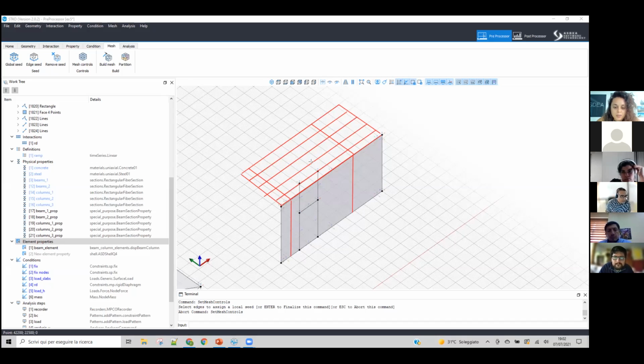So it's actually a bit complicated, because we still need to test very well how equivalent frame modeling works in STKO, but maybe the other thing you can do is create 3 beam elements, assign a rigid stiffness to these two, and then here your spandrel section. So you said that it's better to generate three elements, and the two on the sides should be my rigid links, elements with really high stiffness, instead of adding the rigid joint elements that Massimo explained.